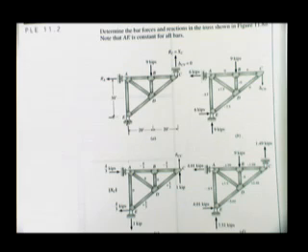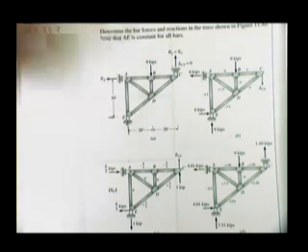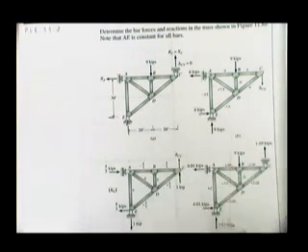So we do the same thing with a truss as we do with a beam. Namely, we remove one of the reactions. Take your choice. I don't know, maybe you could take off anything. You'd have to check. The most obvious one is the one out on the end of the truss, away from where you normally support the thing. So he takes off C vertical.